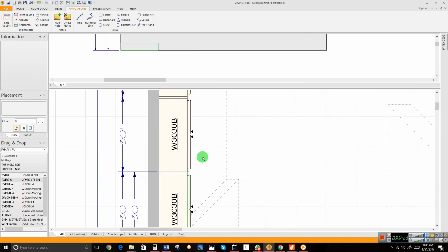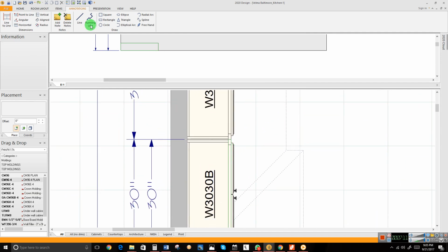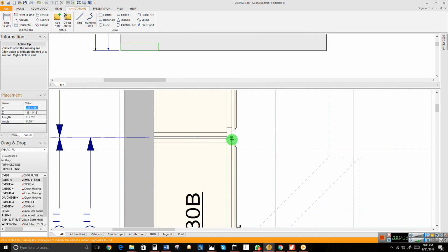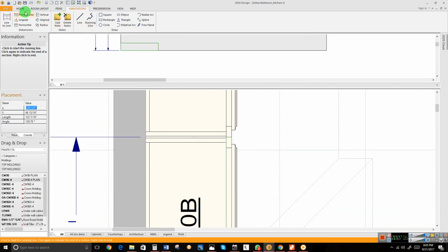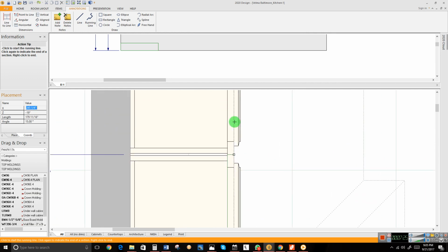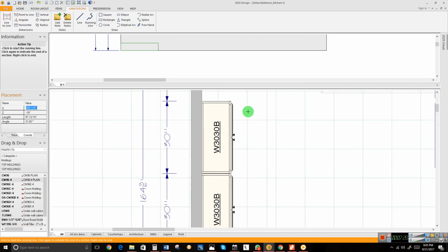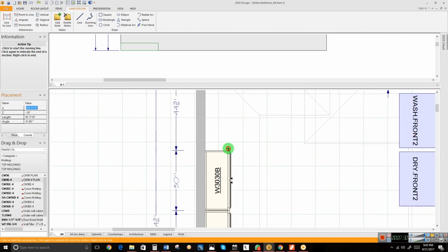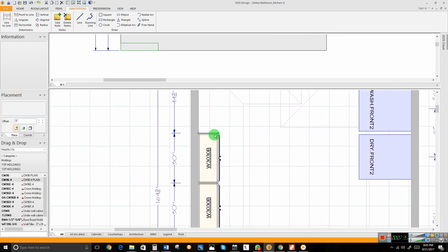So that means if it's the next one I draw, if it's too long, I have to do another one, making 3. Now this is very useful. It's a cumbersome process, but it's good when you're dealing with multiple. Now I clicked on running line again to continue my snap at the same last spot this first one ended. So click there and you keep drawing up again. All right, I'll take it to the end again, snap there, and to the end, snap there, right click, and that ends it, right? Right click again and go to make 3D.